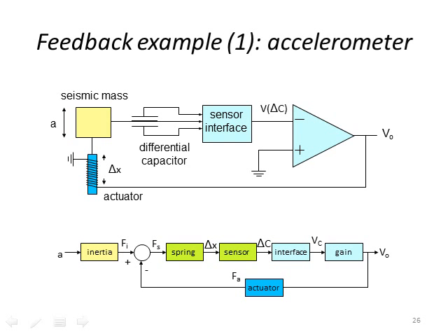And then we have an actuator on the bottom, in this case, that pushes the mass back to its zero location. So the feedback signal that we detect is the voltage that's required to bring the mass back to its original location. So this is a real feedback path. And in this case, this is similar to a nulled output in that when the mass changes, we're going to get an output voltage. That output voltage then will drive the mass to come to its original location. So it changes, you can respond, and it brings it back to its 0 point. And then you measure that voltage change due to an acceleration.